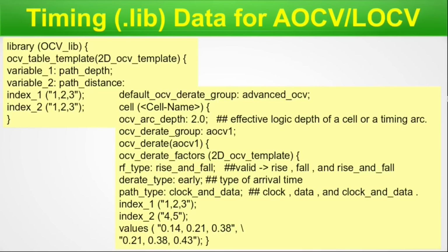So this is a short and sweet description of the data that can be found in the timing .lib, which has to be characterized by the standard cell characterization, and this particular data requires a lot of effort. There could be various variations even for the same cell. So every possible combination has to be logged there inside the .lib. So I have just given you one snapshot.